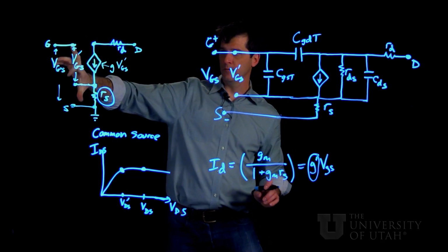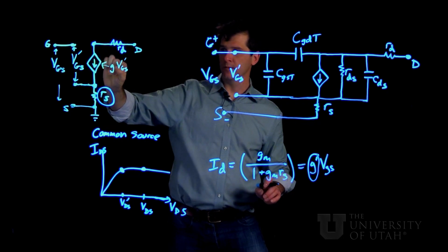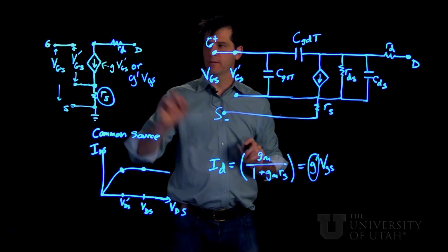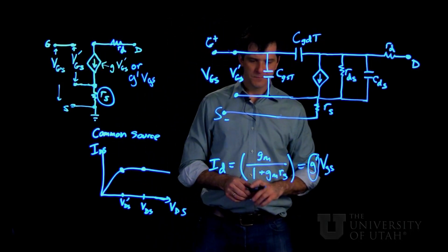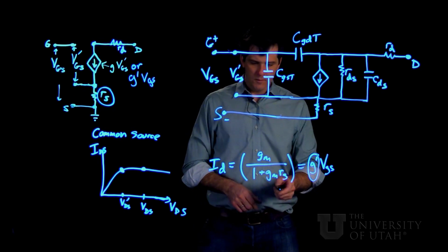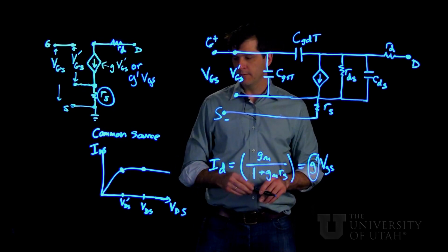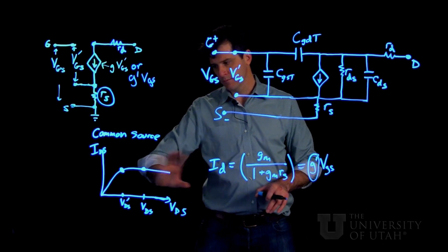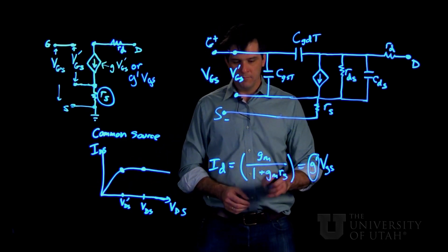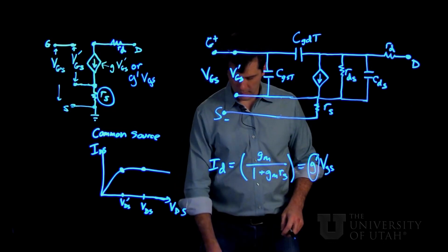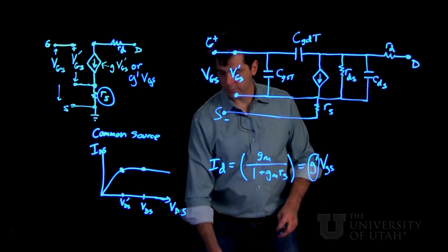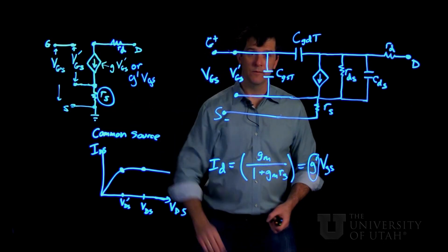We can look at the external voltage and then lump all the changes into a modified expression for the transconductance itself. So what this means is the amount of current you get is in general lower because of the driving potential, which is actually applied across the channel.